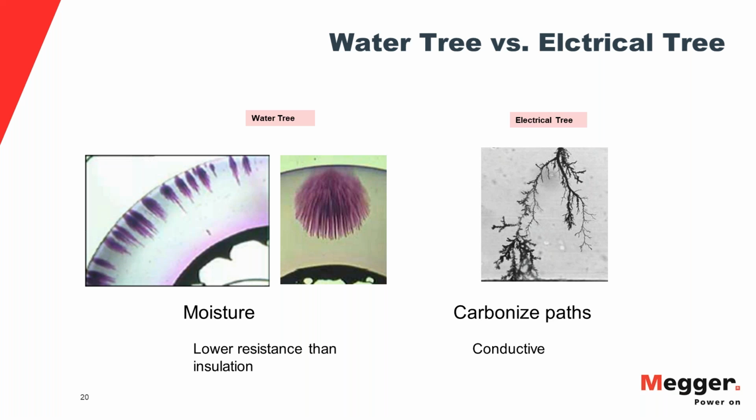And again, with the latest generation of polymer cables, it is very slow, okay? Compared to the original polyethylene cables, PE cables, treeing is minimal, but it still happens over time. It just takes very long. At the VLF, it stresses the insulation, and if there is no critical length water tree that could cause a conversion to electrical tree, nothing really will happen during the test. And then you come back, and maybe nothing happens the next time, and you come back, and maybe nothing happens the next time.